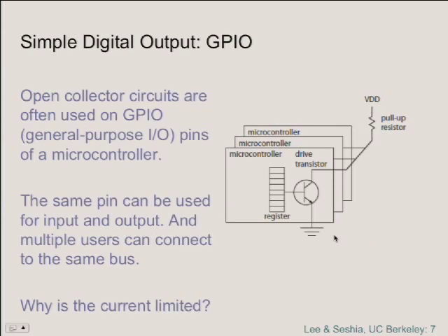Well, the first line of defense is an electrical issue. You don't want one of your devices to be asserting that the voltage is 0 and another device asserting that the voltage is 5. Why not? You have a short circuit, right? I mean, you want the wires in the bus ideally to have fairly low resistance, because if they have a lot of resistance, they'll introduce propagation delays. The bus will be slow. You'll have to consume a lot of power to drive the bus, etc. So you want them to be low resistance.